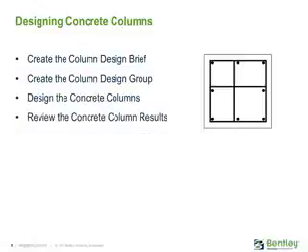In the STAAD Pro Reinforced Concrete Designer, designs are performed on members and slabs according to a set of rules defined in the appropriate concrete design code. The column geometry and loading have been successfully transferred from the STAAD Pro main application into the RC Designer. The other parameters, such as the concrete compressive strength and any reinforcement requirements, must be defined in the RC Designer through a column design brief. Once a design brief is defined, the design group can be created, which will instruct STAAD Pro which members to design and the applicable design brief which should be applied.